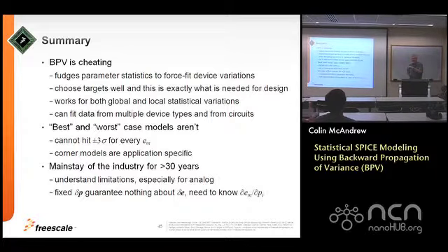And sometimes if things are too nonlinear, instead of simulating a value of a performance, the script does a Monte Carlo simulation and actually returns the variation calculated from the Monte Carlo simulation. So we do statistical or random simulations in that case, but mostly it's deterministic just to get the sensitivities. After you get the sensitivity, then you apply that to your input.